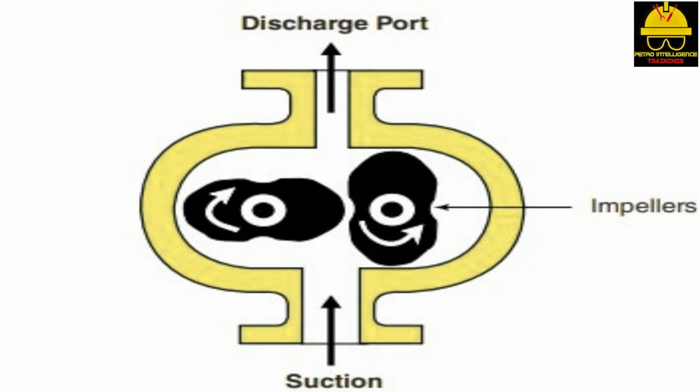The internal lobes on a rotary lobe compressor are designed not to touch. A few thousandths of an inch clearance exists between the casing and lobes. The design clearances on the internal lobes of a lobe compressor allow some slip. The slip is aggravated at high discharge pressure when low-density gases are being pushed. Process slip is constant only when system pressure is constant.